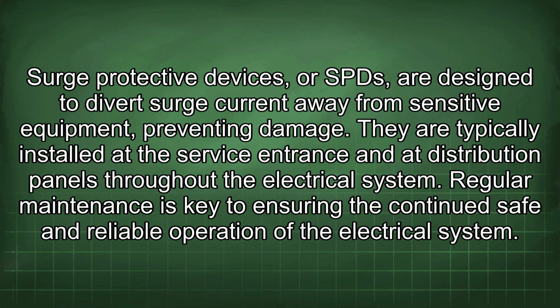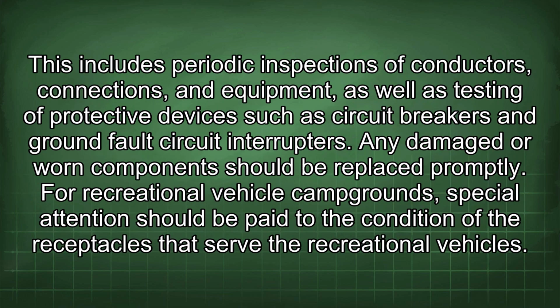Regular maintenance is key to ensuring the continued safe and reliable operation of the electrical system. This includes periodic inspections of conductors, connections, and equipment, as well as testing of protective devices such as circuit breakers and ground fault circuit interrupters. Any damaged or worn component should be replaced promptly.